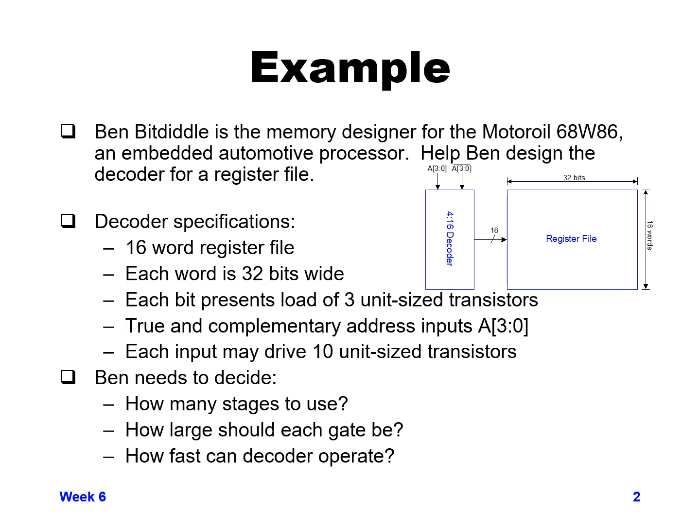So it means you have to drive one of 16 potential selects to select which of the 16 words you might address, and when you select a given word, you have to drive 32 bits worth of value. So you're going to have 32 bits of load on a given line that you're trying to drive.